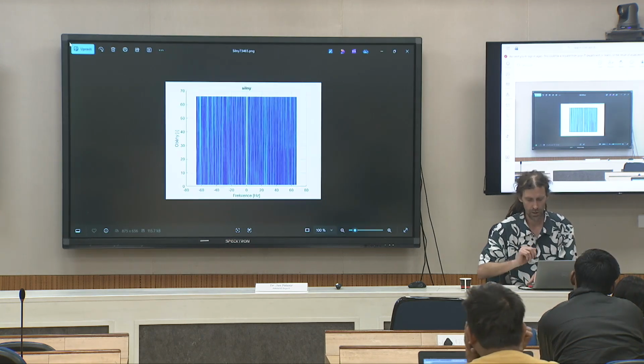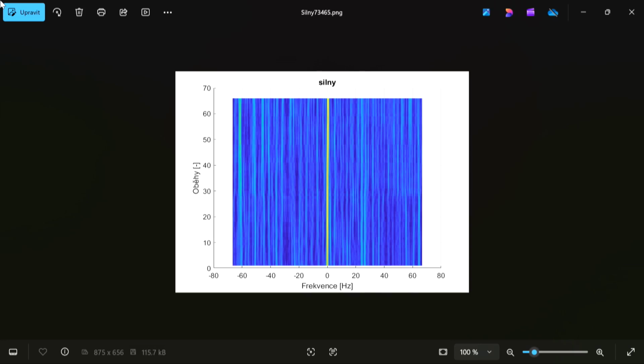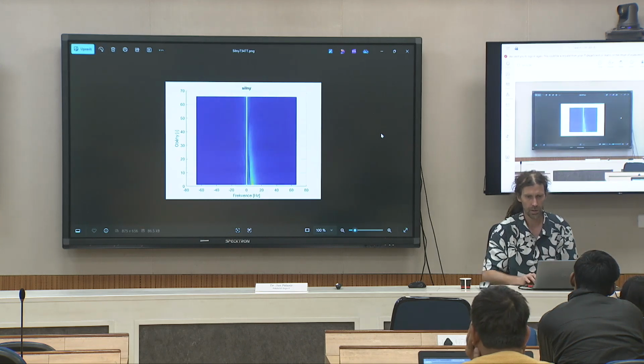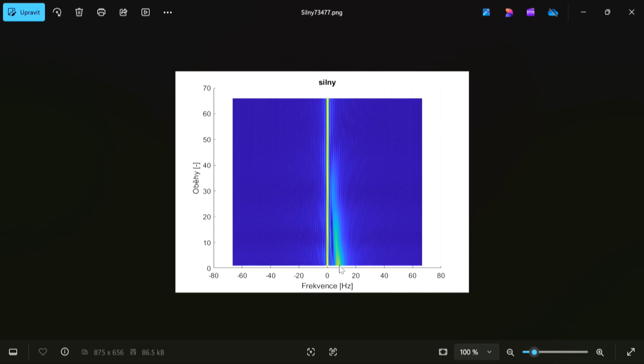This is an individual time shot of our measurement in a range Doppler map. You can see there is something that is not moving, a static object. It will not be a wind turbine, it is just taking a measurement. Now we made some adaptation, and you can see that there is some moving object, because it is already 10 hertz of Doppler shift. So some cars start moving and go away from our antennas.